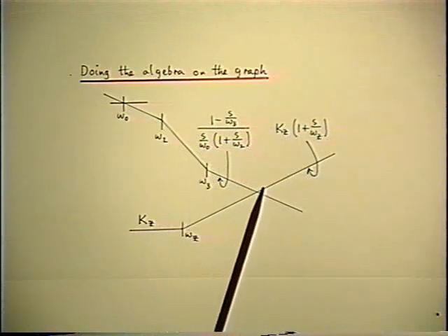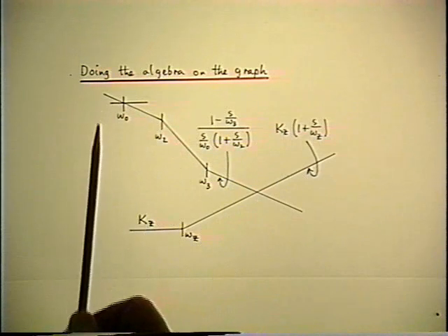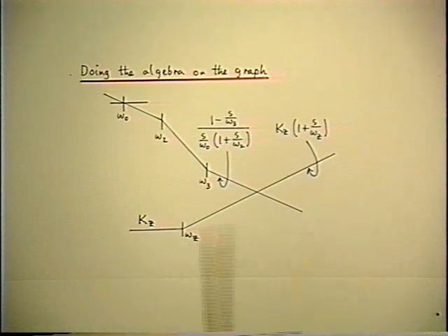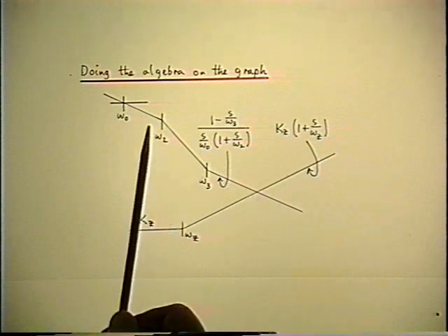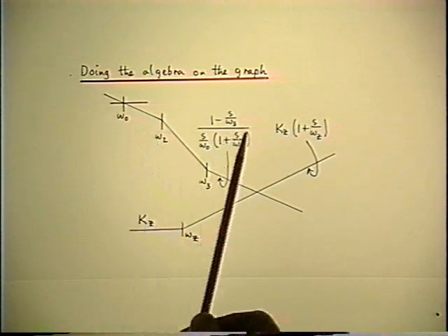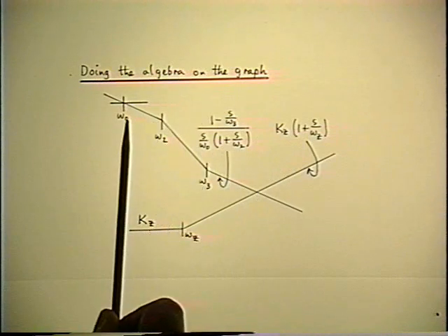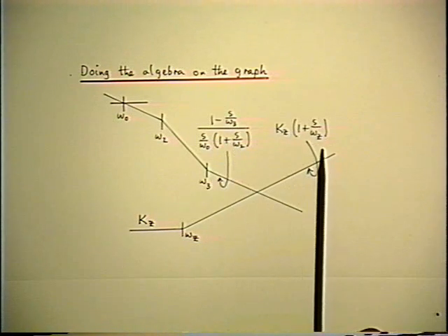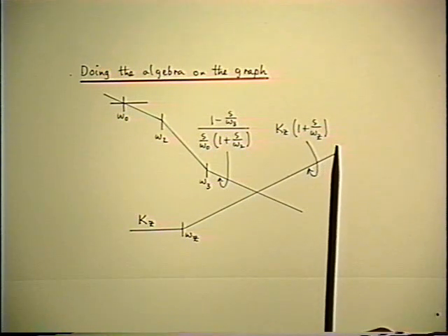Well, when you have a sketch like this, you can see that if you're going to add these two functions together, remember that this is a double log scale. This is dB vertically versus frequency on a log scale horizontally. So it's really a double log scale. So whichever function is largest is certainly going to dominate the sum. So at relatively low frequencies down here, the left-hand function totally dominates the result. And the opposite is true if you go to high frequencies. Now the other function dominates the result.